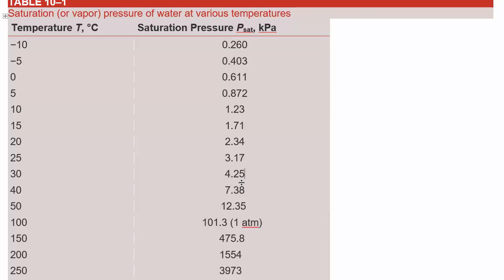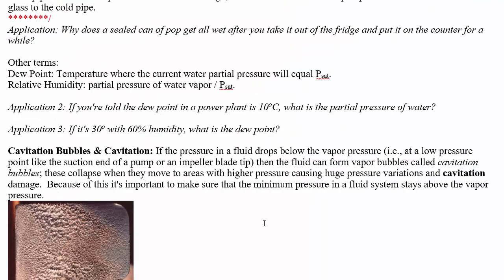Well, at some point, the pressure inside the liquid is going to lower below the saturation pressure. Since liquids are pretty incompressible, if you actually pull apart the container, that's going to happen pretty quickly. It's going to stop being 1 atmosphere of pressure near the top and then some hydrostatic increase near the bottom, and go quickly a lot lower than that. And you'll find that water will start to form pockets. This happens inside pump systems too, and it's called cavitation.